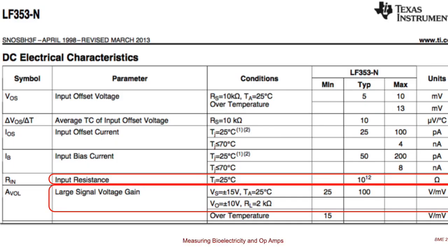When we think that electrode resistances, which were important to us, were on the order of kilo ohms to maybe mega ohms. Not unusual to have a few mega ohm resistance. This is a million times bigger. A million times bigger than the biggest resistance you'd typically ever find or use or encounter. So this is big. This is close enough to infinity for us to treat it like it's infinite. This is not too much of an exaggeration in practical terms. Now the second value is the A value, the amplification value.